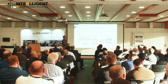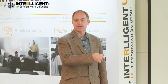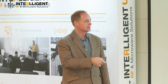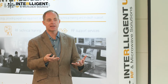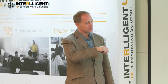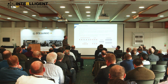The key isn't necessarily being able to lay these out. The key is being able to model these and how these parasitics all actually get impacted when you do this. We've done a lot of work on our modeling side so that as we scale these devices with geometry, we're actually taking that into account in how the device is modeled for design purposes. So we get excellent correlation as you scale these, both in geometry and bias, to measured results.